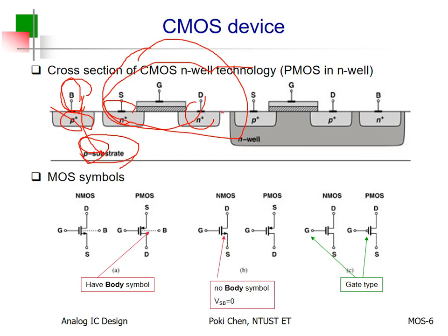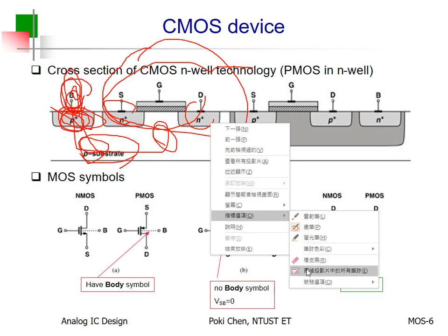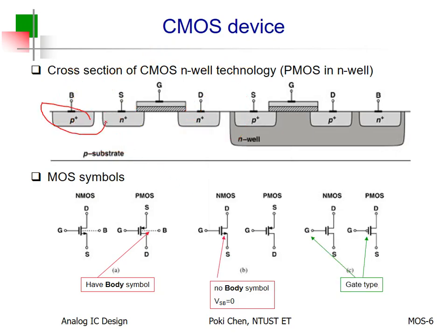So they need to be doped as N plus with different types. Okay? And how about your body contact? Don't forget, the body contact helps you to conduct the voltage from here to there, right? Don't dope your body contact with N plus. Otherwise, you will have another diode.